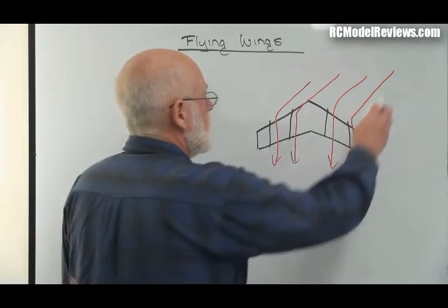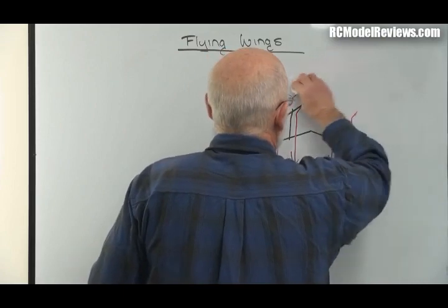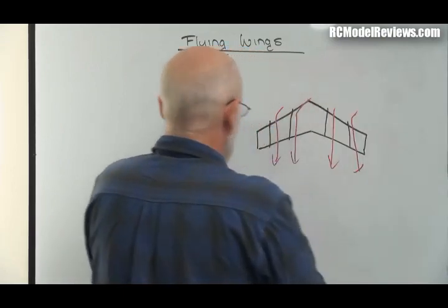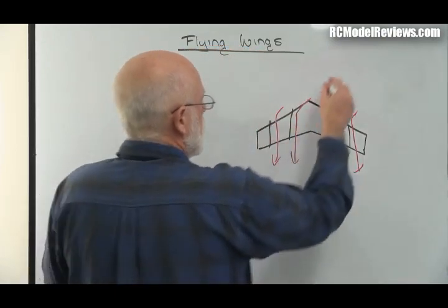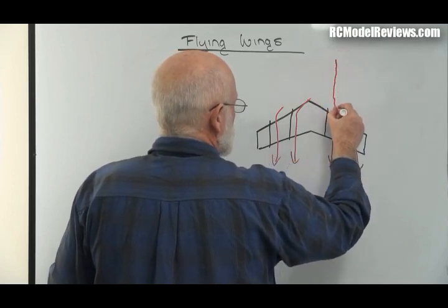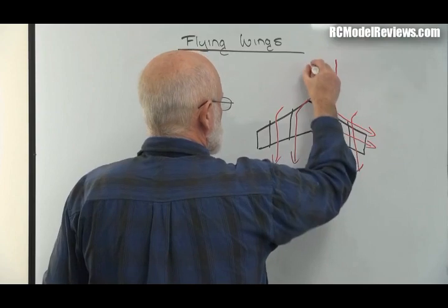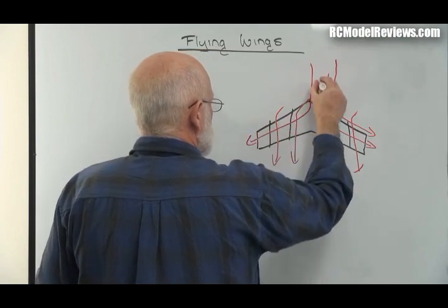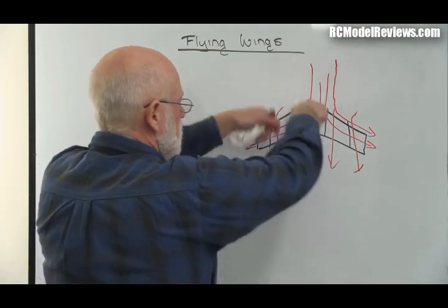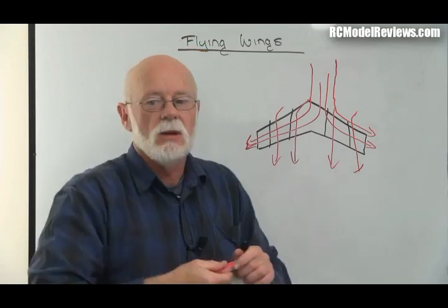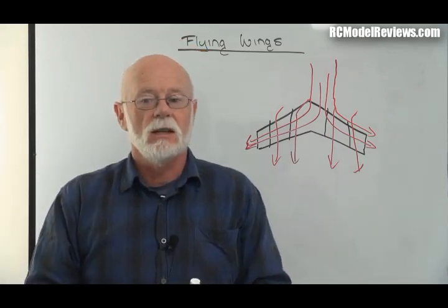Another factor is that even when you're flying forwards with a conventional swept wing, you get air coming in like this, and without the wing fences it tends to follow the sweep of the wing, so you get air flowing towards the tips because it's being directed that way by the wing. So you have this spanwise airflow. Spanwise airflow is really bad. It's not a good idea. You don't want that. It's not good at all.